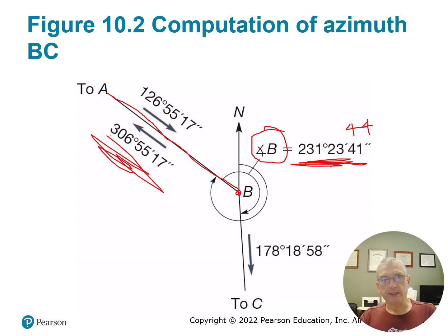Software makes it really easy to compute a raw angular error. We'll always do that, but error of closure, where we're able to figure out what the horizontal error is, which we're about to get into, is if we did not adjust our angles. What we want to do is adjust our angles first and then use our adjusted angles to compute our azimuths for our traverse computation.